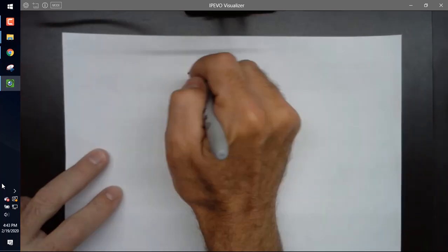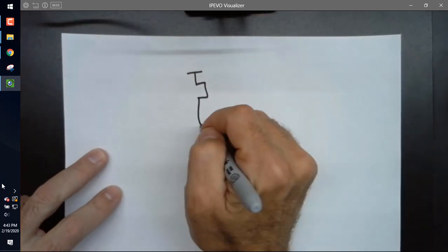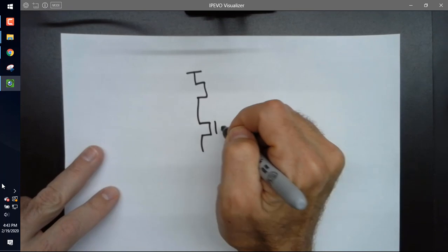Let's talk about why we need a startup circuit. This is called a self-bias circuit. So in any self-bias circuit, if you took 421, the band gap we designed, that was also a self-bias circuit, and there was a startup circuit in there, and I want to explain that to you now. So if you look at the following, which is the beta multiplier we just talked about, multiplying up the beta.